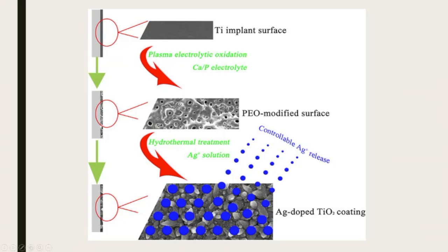There are many materials that serve really well for some of the requirements for bioimplant materials, but are not very good for others. For example, calcium phosphate-based ceramics show a great deal of biocompatibility, but their undesirable mechanical properties like brittleness, low strength, and low fracture toughness have limited their applications in load-bearing cases.